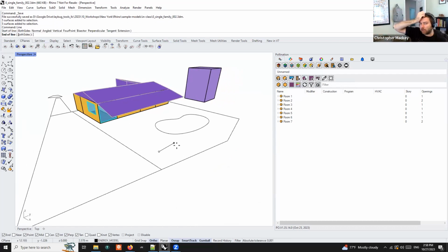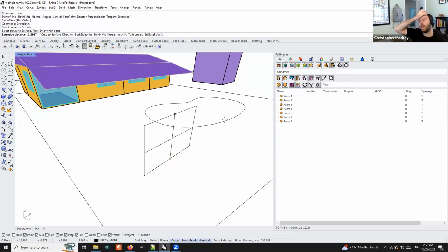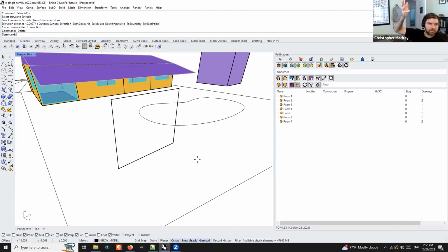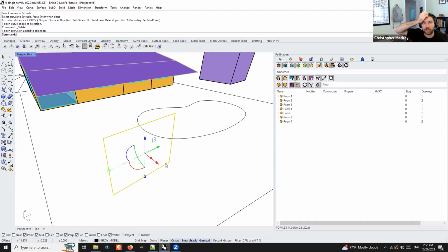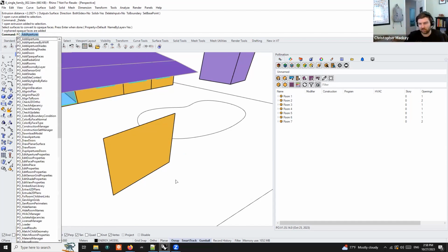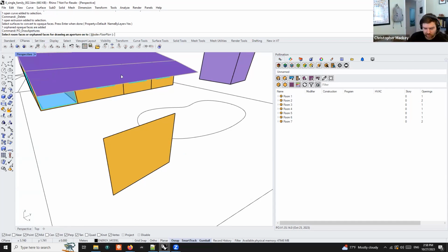Honestly, it doesn't really affect the simulation that much to assign it to a specific object, but it can be useful. For example, in the really advanced annual daylight workflows that we have, where you look at daylight within a specific room, you can assign the shade just to that room, and that shade will only be part of the calculation of that room.